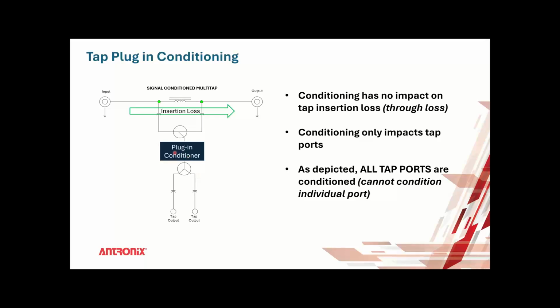Okay, that's what you mentioned. Yes, when you mentioned this choke was missing, no. If this plug-in is missing, you definitely will not get any signals in the tap port. And if you pull it out, it will also affect your insertion loss, because keep in mind your RF, this is a 3-port device, this directional coupler.